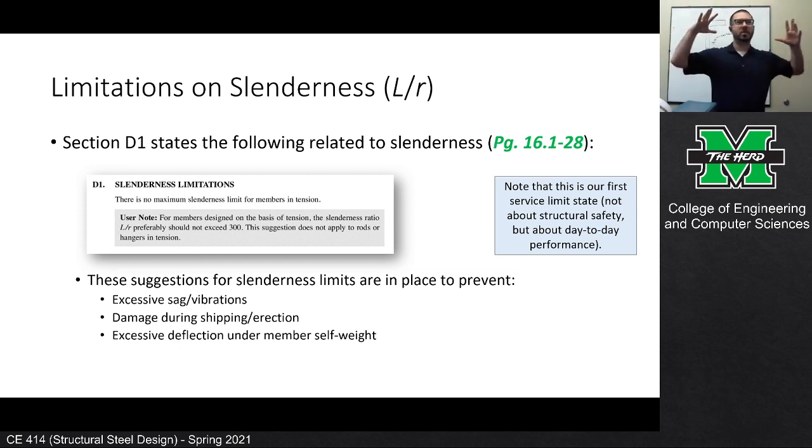Steel in its intact, erected, structured system state can be a pretty stiff system, but as you're putting it together, steel can be a little tough to handle if it's really slender. The members can have damage during shipping, damage during erection. If you've ever been in a fabrication shop and you see them fabricating a plate girder, when they're manipulating the plate, that plate picked up the wrong way can have about as much stiffness as a piece of wet spaghetti. So it's kind of strange.